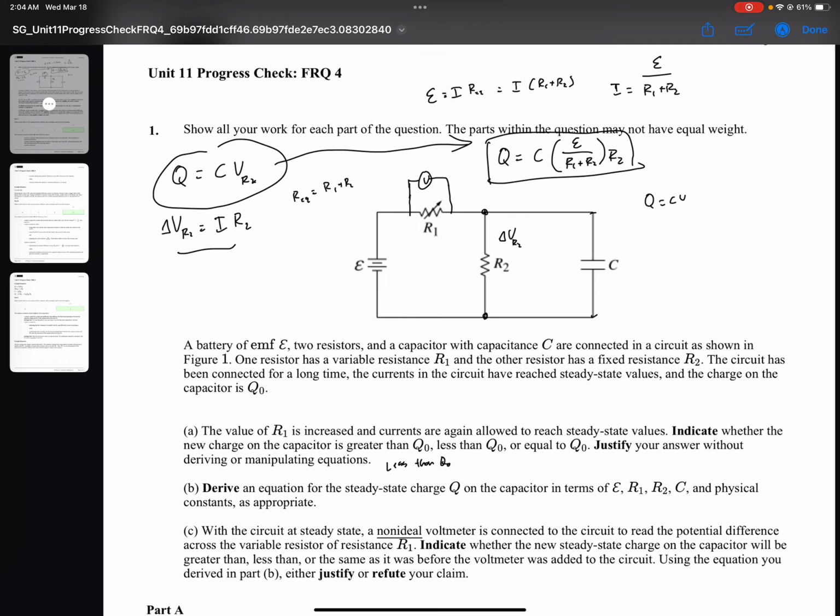And as you know, the equivalent resistance for resistors in parallel is this equation. Let's say R2 is the resistance of my voltmeter. Well, if it's infinite, then it doesn't really affect my circuit at all, right? Because 1 over infinity is 0. But if it's a very large resistance but not infinite, then it does affect the circuit a tiny bit.